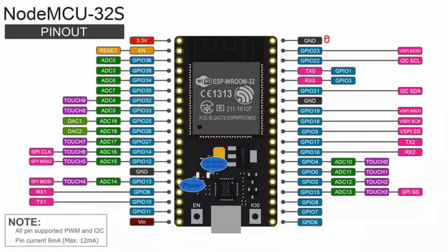When it receives the signal, it is acting as an input pin. So you can use this pin as an input pin as well as an output pin. And there is a power supply. You can see the power supply, 3.3 volt you can give. So 3 ground pins are there. You can use any of these, and then VIN is the 5 volt power supply.